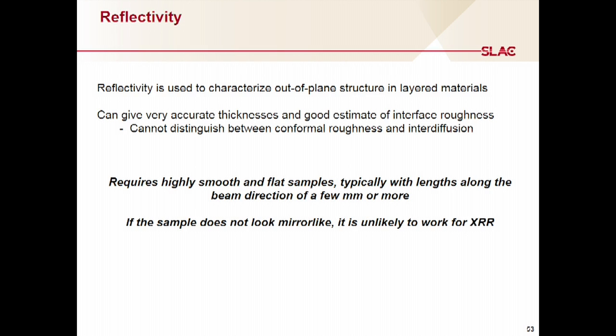And the sample requirements for reflectivity are fairly high. You need something that is very smooth and very flat. And so a necessary but far from sufficient condition is if you look at your film and you cannot see a good reflection that looks like a mirror, it's almost certainly not going to work for reflectivity. Now, even if it's mirror-like, that doesn't mean that it will work for reflectivity, but it's at least a very good starting point.